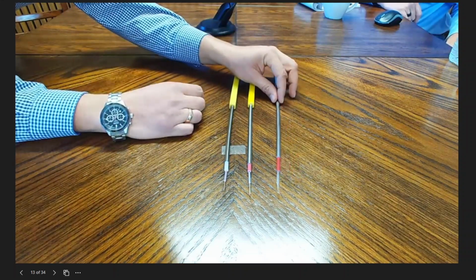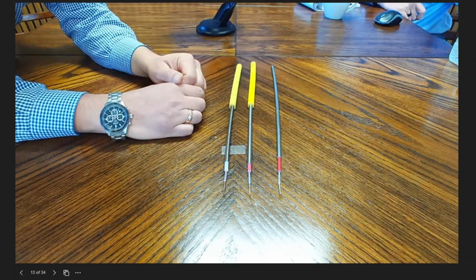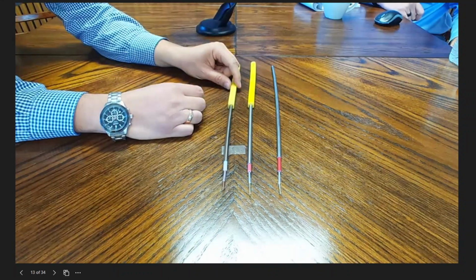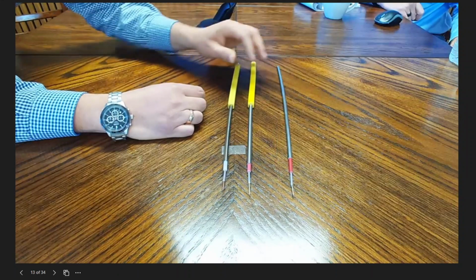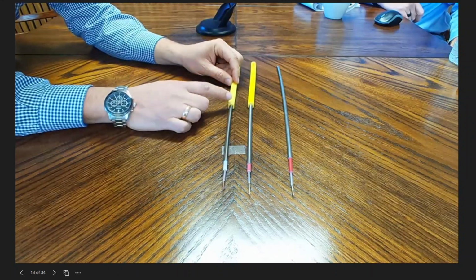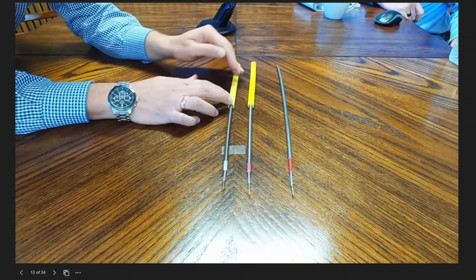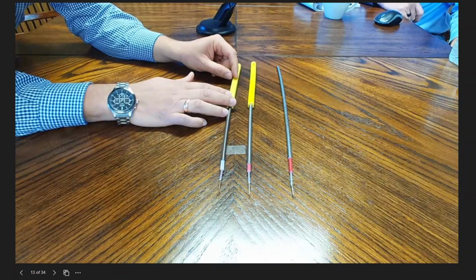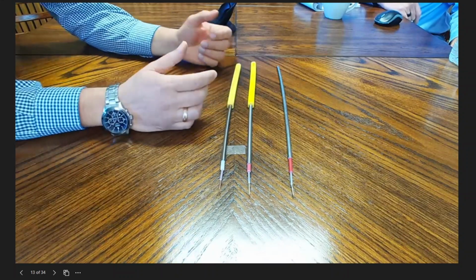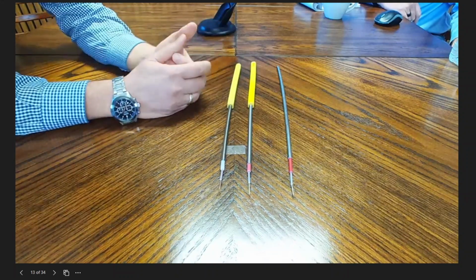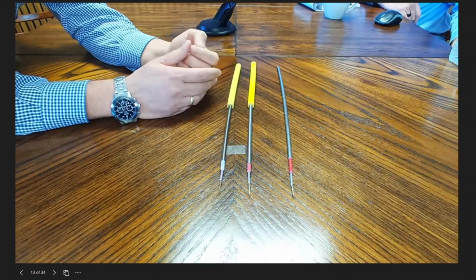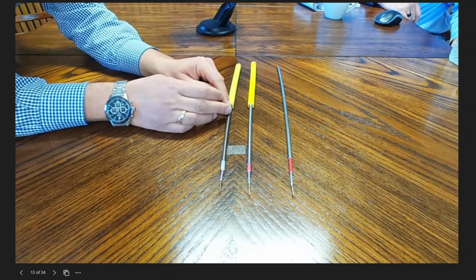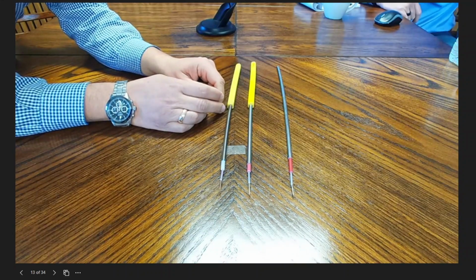This is quarter-inch OD, 0.25. The encapsulation is an extra layer of protection over this armor. Believe it or not, this material is hard, and when you have a mechanical impact, it absorbs the energy of that impact substantially. So it reduces the impact on the armor of the cable. It's like a sacrificial protection.